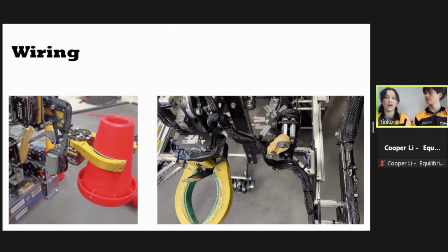We actually only have 2 connection points on our robot. We have a connection point from the servo, where we wrap the servo wire around the servo until it lies flat. Then we have custom wiring all the way to another connection point at the end near the turret on our robot. We found this really useful because if one of our servos didn't work, we knew exactly where to check. There was no chance that it would be in the middle of those connections.